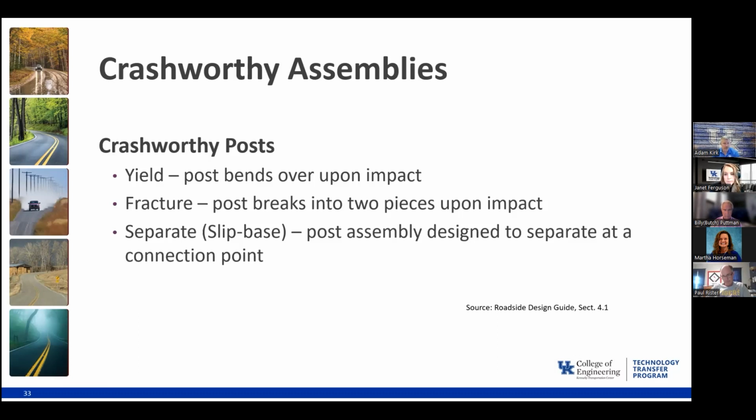And then the other crash-worthy assembly is the slip base. We saw that earlier, where you've got an anchor joined to that post assembly with a bracket, and that bracket will essentially shear off at the connection point.